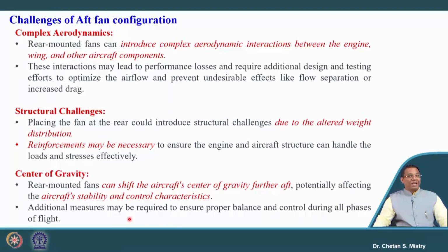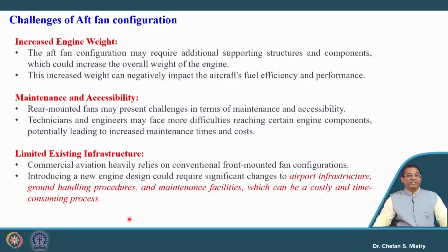Okay, so proper balancing and control may be required for all the phases of our flight. Okay. Then it says it will increase the weight, because additional support structure is necessary in this configuration. So, other than engine weight, we will need to put additional components for the fixing of this engine, and that will be increasing the weight.